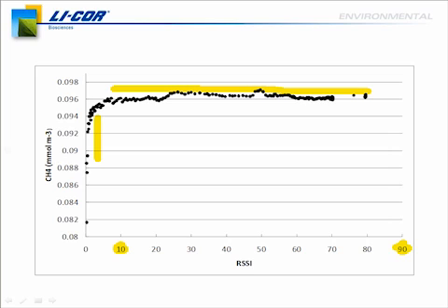And I should have mentioned the cleaning fluid that we're using is just very basic. It's just a mixture of water and alcohol so it doesn't freeze. You can use automotive windshield washer fluid. We use that at sites as well. So it's very flexible. There's nothing special that you need to look for in a cleaning fluid or anything like that. And like I said, the frequency that you're going to have to change or add fluid to the reservoir just kind of depends on the environment you're in.